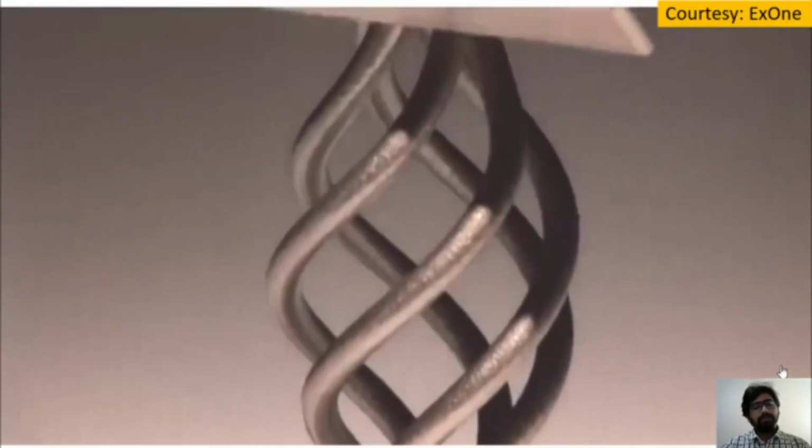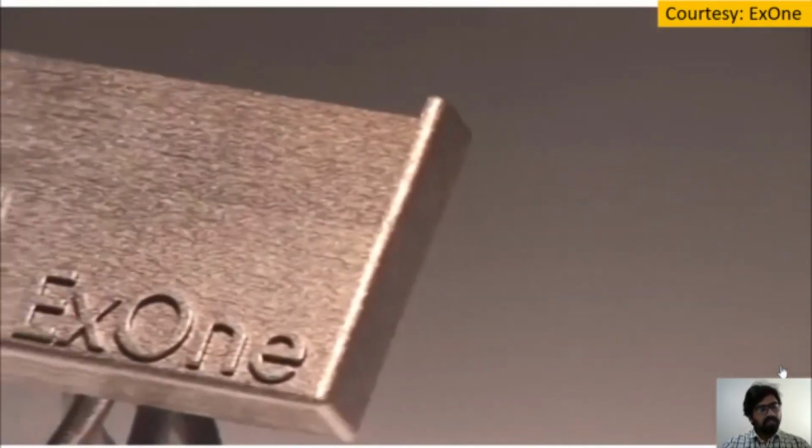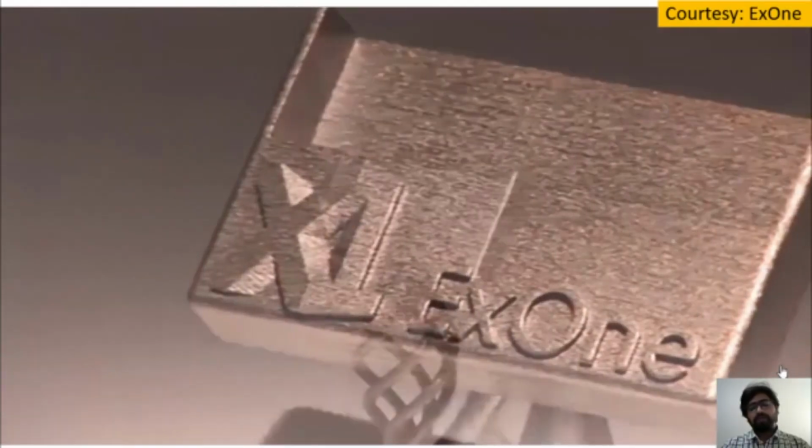Some sand got trapped into very intricate areas as well and has to be removed, and of course some portion of the part produced by this technology has to be further finished by an appropriate machining operation. So this is a very important application of binder based powder bed additive manufacturing, of fabricating direct molds without utilizing any pattern for creating the molds.